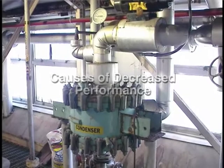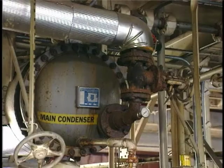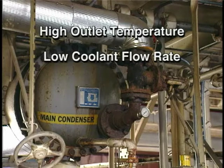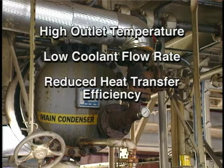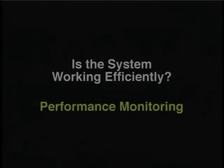There are several factors that contribute to loss of performance in condensers. These problems include high outlet temperature, low coolant flow rate, reduced heat transfer efficiency, and buildup of ice or frozen organic compounds.